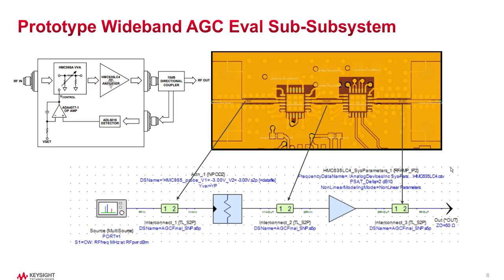This is a section of the board in ADS layout. But you can see there's these sections in the top where the top metal was cleared away to make some connections, causing some inadvertent resonators. Some of the ground returns around the signal paths weren't ideal. There were even some issues with the thermal reliefs that were applied around the SMA connectors, the RF connectors. These parasitics can be represented in these layout interconnect models in our SystemVue SpectraSys simulation.